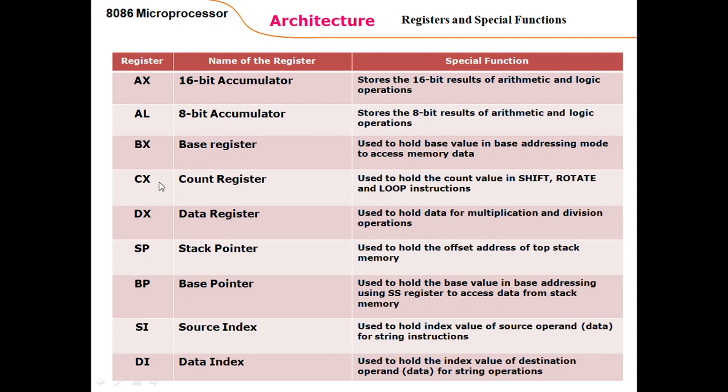Similarly, the CX register can be used in arithmetic and logic calculations, but there is a special purpose of the count register, and that is to hold the count value in shift, rotate and loop instructions. For example, if one is to rotate or to loop to a certain label a particular number of times, then that value is added to the CX register, and each time these instructions are executed, the count register is automatically decremented by 1. The data register, as the name specifies, holds data for multiplication and division operations.